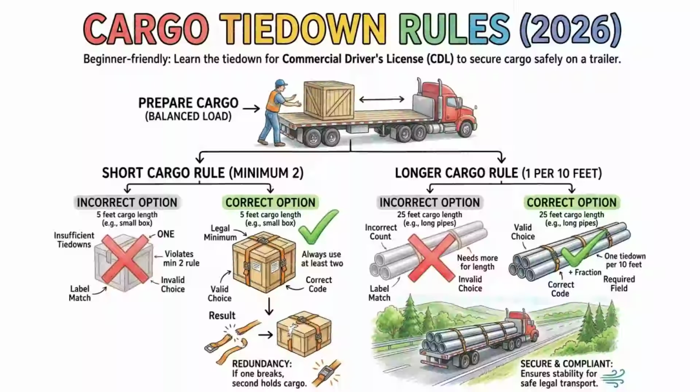Discharging passengers safely is just as important as boarding them, especially in busy urban areas or on dark rural roads. When dropping people off, you must pull as close to the curb as safely possible so they can step down securely. After they exit, you must carefully check your mirrors to ensure all departing passengers have completely cleared the area and walked safely away from the side of your bus.